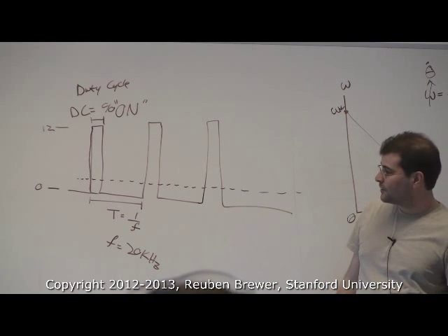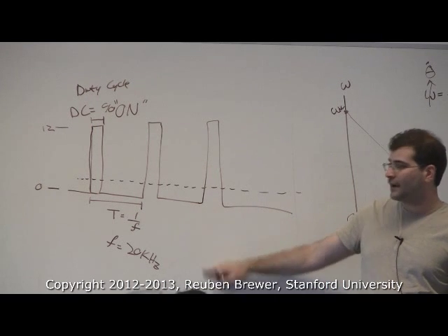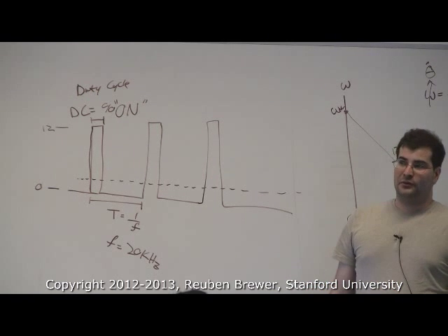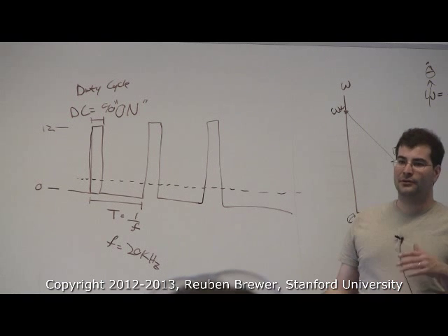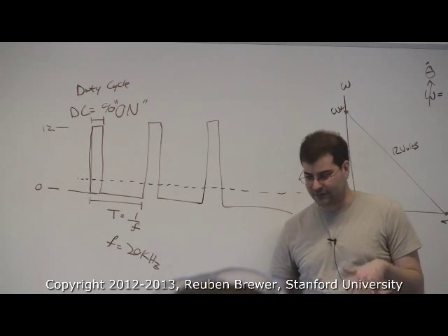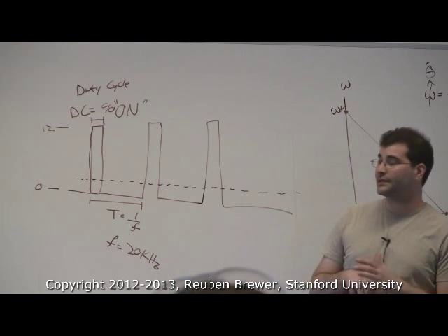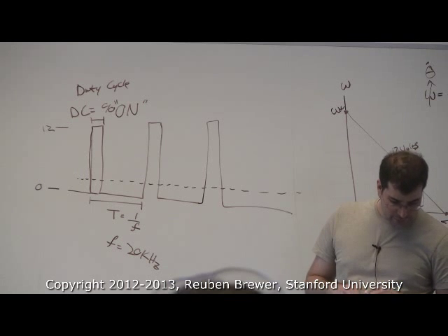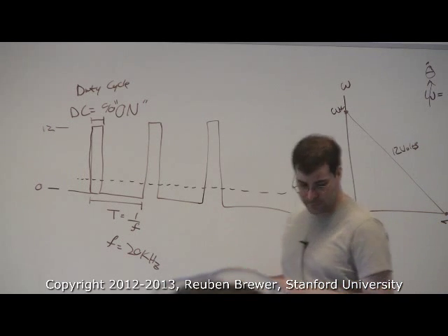Okay. So typically, if you're using a DAC card, you just say what percentage it is. With microcontrollers, you set output compares to give you percentages, etc., etc. They also usually have some type of special PWM generator to make it easy. But practically, there's a pain here.